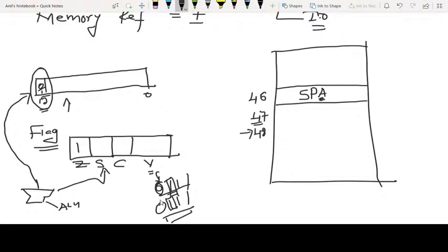Now, whenever the overflow digit is equal to 1, it shows an important status of the output of the instruction from the ALU. The ALU computed, and due to the limitation of the size of the register, the actual sign has been reversed. So whenever the overflow digit is equal to 1, the sign has to be reversed.